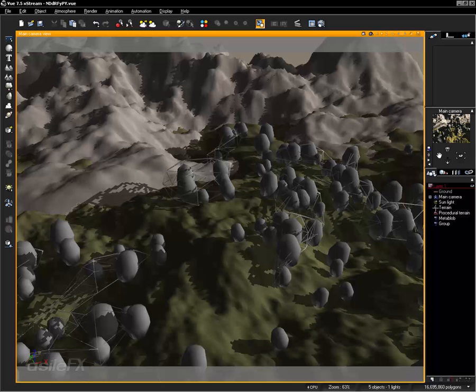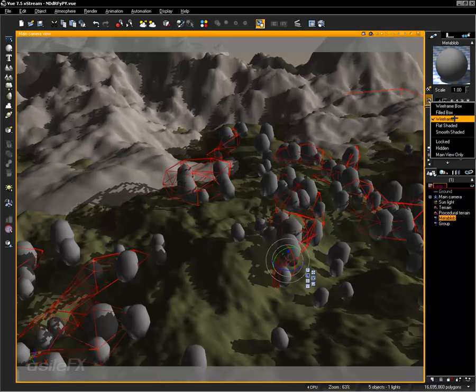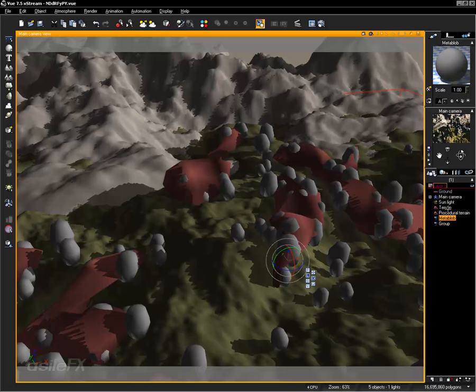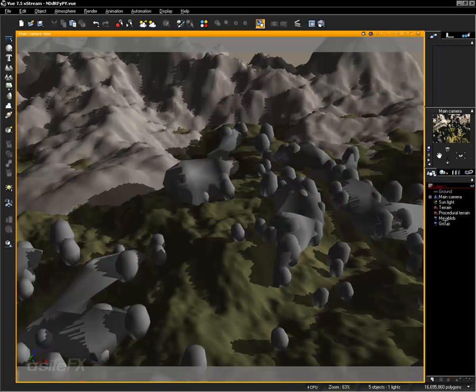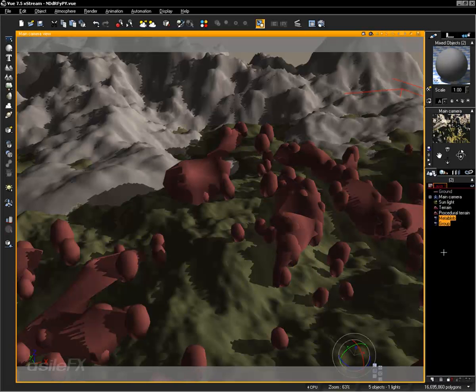It could just be a display error, or what is selected for its view mode. And it looks like it's set to wireframe, set that to smooth shade, and now it's fine. So we can take these two objects, and you can save them out separately if you want to set different types of collisions to the smaller separated objects rather than the blobs.